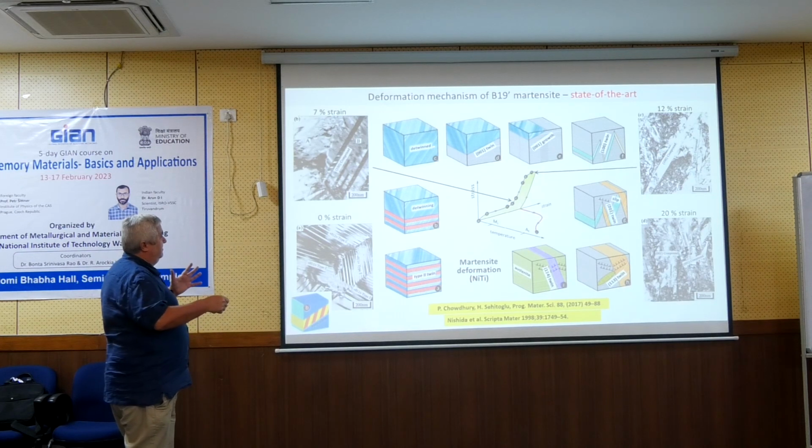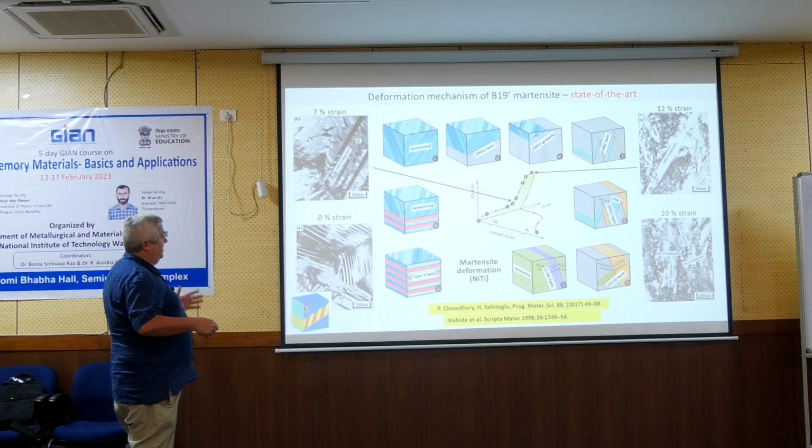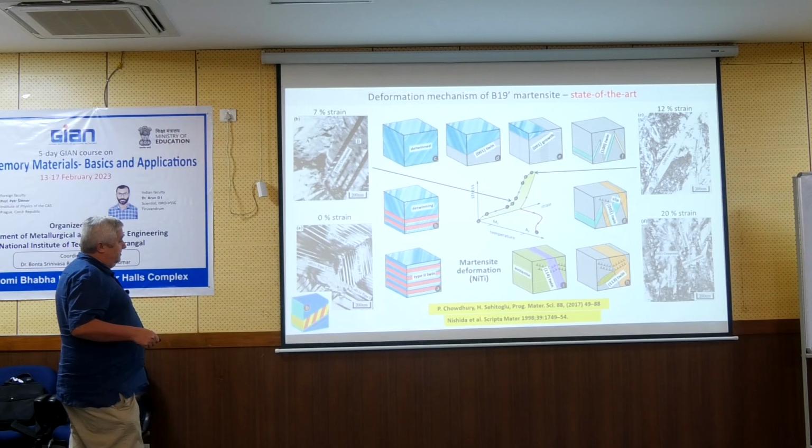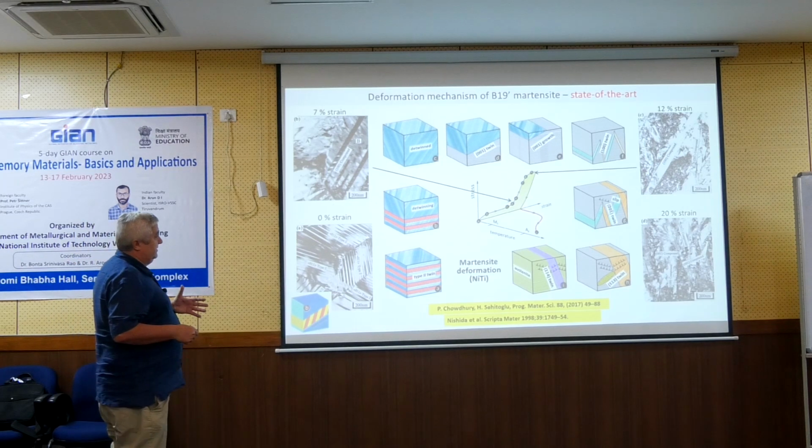So they think about the plasticity of martensite. They take from the literature the information about those deformation bands, which other people have seen as well, and they combine it into this scheme, which is almost close to what I will be talking about, but not exactly, because they are bound to this type 2 twinning, which is observed in single crystals.